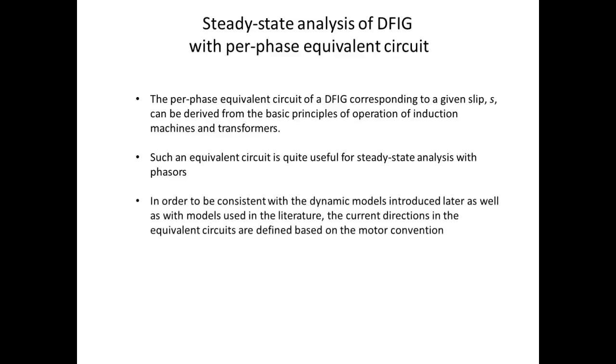Okay, I should also mention a note about the conventions used here. Many of these dynamic models and control techniques, like the field-oriented control, were developed for motor drives, meaning the machine is operated in the motoring mode. So for example, the power drawn from the grid and converted to mechanical power in the motor would be considered positive. When these concepts were later extended to the generator mode of operation, the same convention was continued.